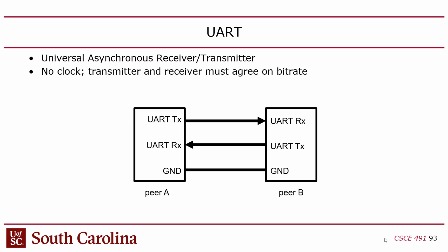So how do they get away with it? Well, there's two reasons they can get away with that. Number one, they run these very, very slowly. So the baud rate, which is the rate at which data is sent, is in the kilobits per second, kilohertz. Whereas SPI, I didn't talk about this one, I never mentioned what the clock rate was on SPI, but it's fast, real fast, megabits. I've seen SPI go like 10 megabits, 100 megabits. SPI is fast.